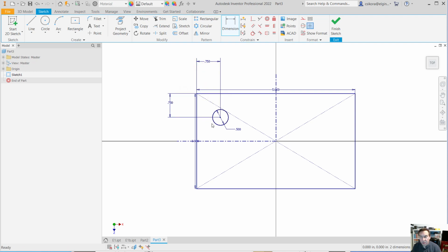All right. Now, stay away when you drop from that center line there. That one you don't want to be attached to. If it is, you can actually delete the constraint or just click on the circle, redraw it. Sometimes that's easier. We're going to learn more about deleting constraints another day. All right, now we want to mirror this across.